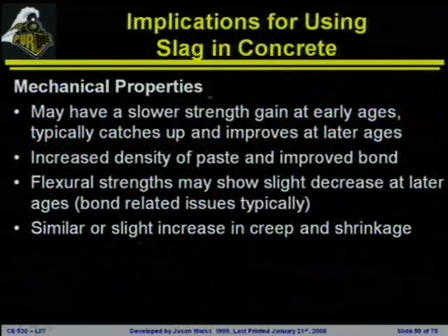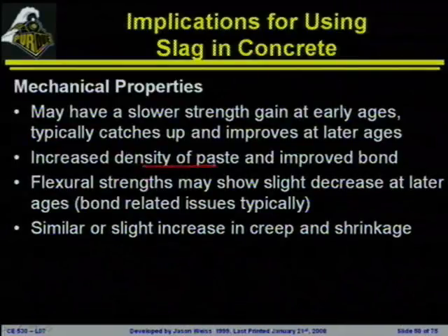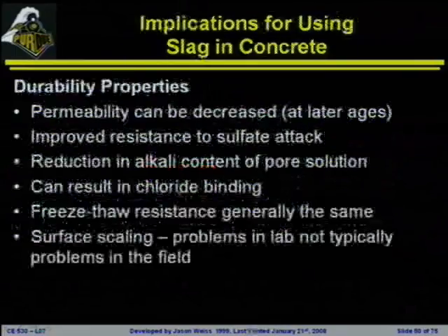Mechanical properties are going to be very similar to your ordinary Portland cement. The paste will become a little bit more dense. Again, we've got a supplementary material that's undergoing a pozzolanic reaction as well as a cementitious reaction. And the other mechanical properties are typically very similar.